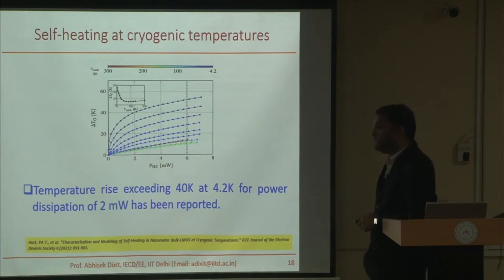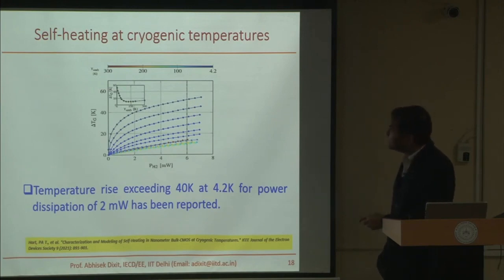Yes, that's what we are seeing, right? So thermal resistance increases, that's why the delta T is increasing. So far, as I said, the prevalent view is that this is black body radiation kind of a thing. So you are not able to carry all that heat out, right? So a phonon is leaving the channel, leaving the hot area without much scattering events. That's basically what people are saying. Okay.